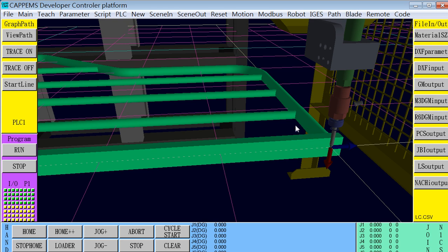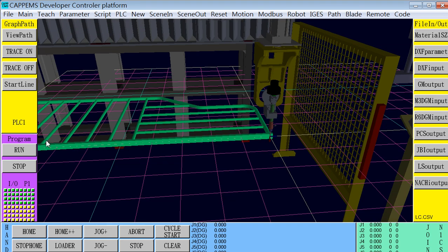and this side is the same. Straight down, turn B, turn C, and inclined weld the first point, and along the circle lift to the top and retract back, turn the B axis and C axis back to 0 positions, and combine these two weldings for one full round circle welding, and the rest from here to the end all use the same methods.